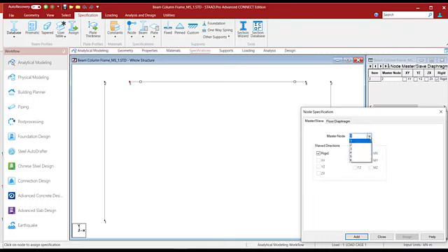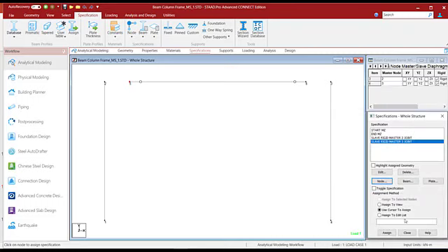In this case, the master node is 3. So we click on add, and once that is done, using the assign to cursor option, we can select node number 6, and thus the master-slave relationship is defined. Now, if we highlight the assign geometry, click on the first option, we can see that node 2 and 5 have been defined to be in a master-slave relationship, where 2 is the master node and 5 is the slave node. Similarly, for node 3 and 6.